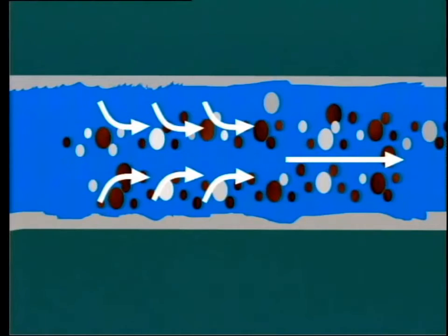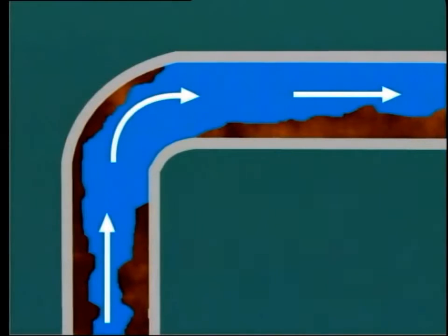The removed metal, products of corrosion, can also cause a problem, as this material now increases the total quantity of solids contained in the boiler water. As we know, this can increase the probability of deposits and scale formation on the inside wall of the tubes. So what are the conditions that cause corrosion and loss of metal inside the boiler drums and boiler tubes?